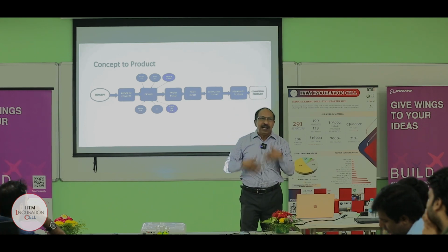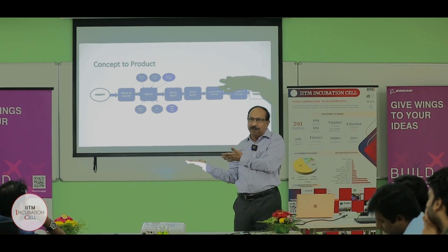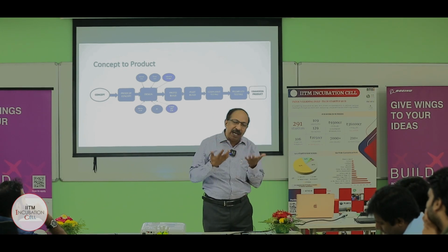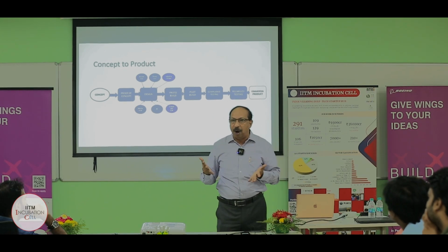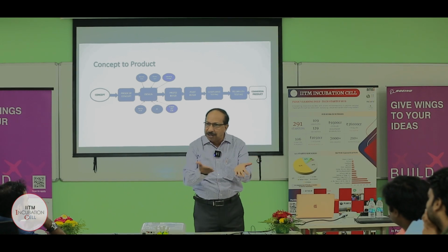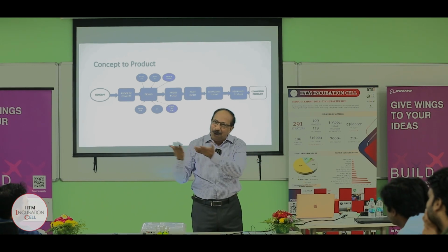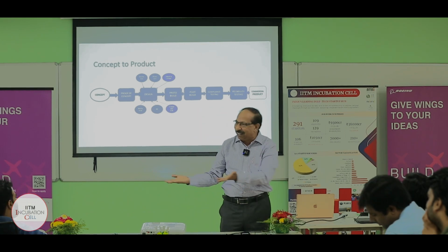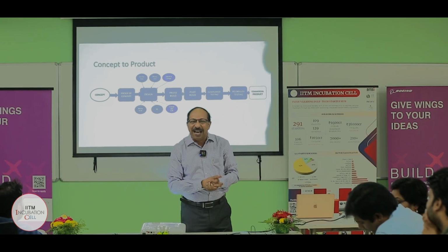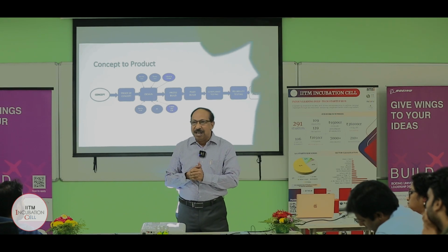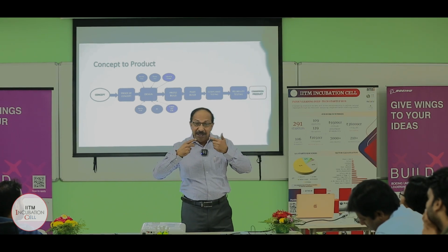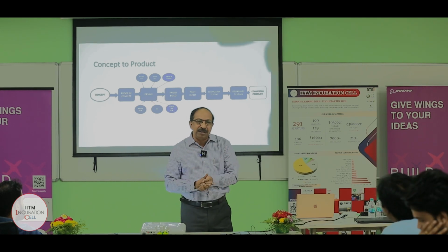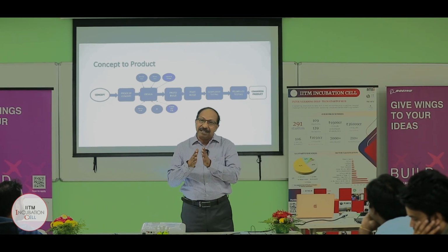Reliability testing. You are coming up with a product, especially for aerospace and all. How can you tell the warranty, the life of your product, because you have not used it? It's a new product. One option is you go to some astrologer and ask him what can be the life, and he will tell you 10 years or something. That is not going to happen in science. So you have to accelerate the life test. That is called HALT, highly accelerated life test.